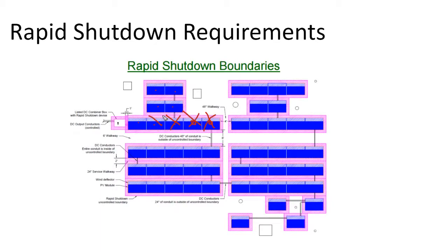So on a roof, it is wise to use module level panel electronics despite the added failure points and slight cost increase. On the ground, detached from the building, the use of module level panel electronics, particularly on an unshaded solar array, is less important.